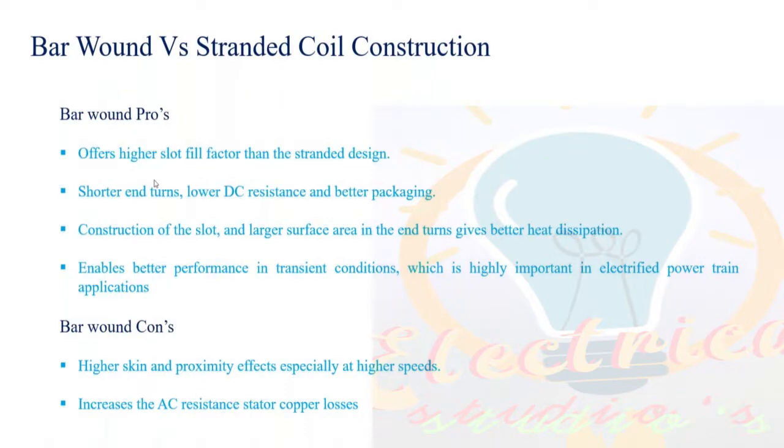Your motor size will be smaller and better packaging is possible when we use the bar winding system. At the same time, when we have such a bar winding system, they exhibit very good performance, especially in transient conditions. Transient conditions, what do you mean?